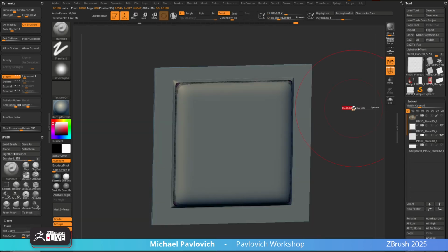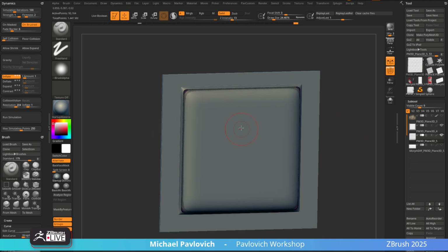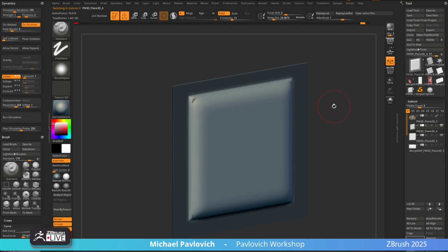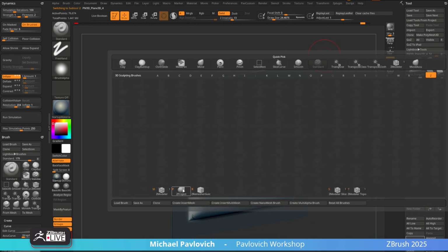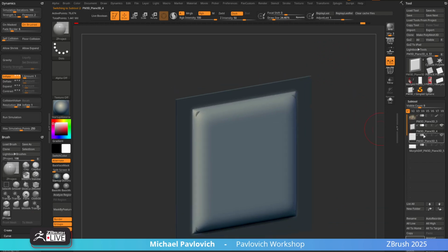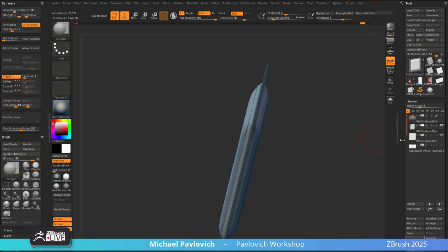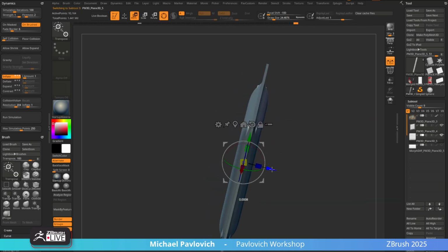Now, we have something that we want to snap another piece of geometry to, or project another piece of geometry. One easy way to do that is with this outer package selected. We can go to BZP, which is your Z project brush. Any visible subtool like those crackers that you have visible, you can go through. Let's scoot this forward just a tiny bit.